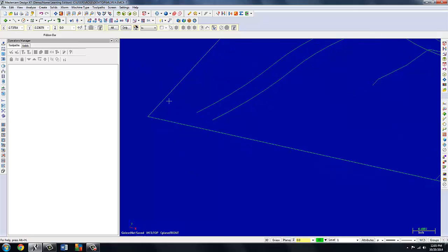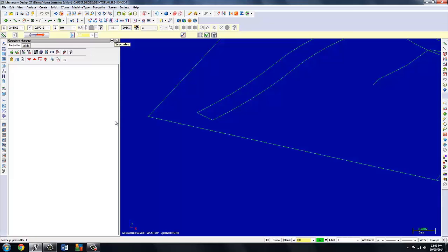Per the drawing, I need an arc radius of 0.2 down here. So before I do that, I want to create a line end point. Make sure you snap to the end of this and the end of that. That looks good. And I also need a parallel line. Because this is done on an angle instead of straight parallel with the front, we've got to control it. Whenever I try to use the 3-point method with the center point, it would draw the radius parallel instead of on this angle.